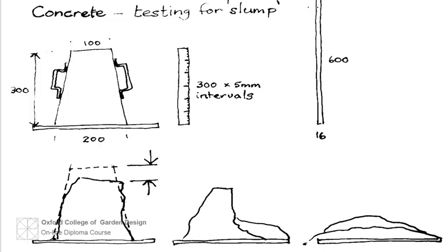Workability can be increased by adding water, but the danger is that too much water leads to a weak, porous concrete. A stiffer mix can be consolidated with mechanical aids, vibrating beams or a vibrating poker. Chemical additives can be used to improve workability with reduced amounts of water.